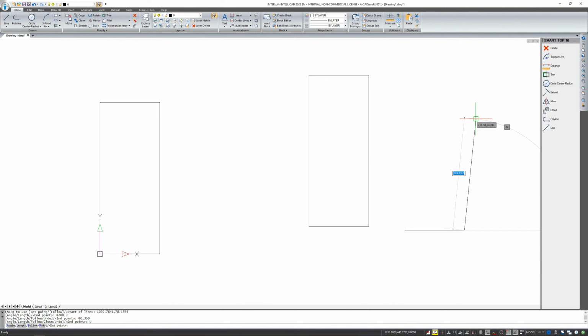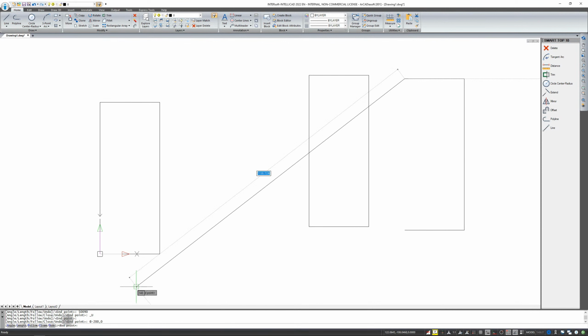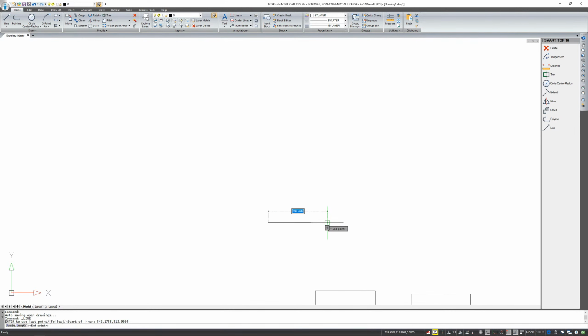When you finish the command, then using Ctrl Z or the arrow in the top left corner, we'll remove the whole entered rectangle as here. But remember that the arrow in the top left corner removes everything from the moment of command activation, both during drawing as well as after you have finished drawing an element. Now I will finish by typing the letter C, which means I finished my drawing. You can use the tab and input window to draw angles, but you don't have to, and you can select options from under the arrow.